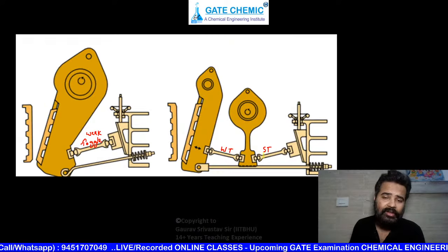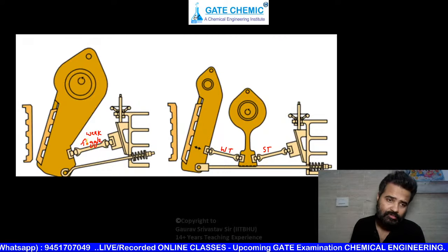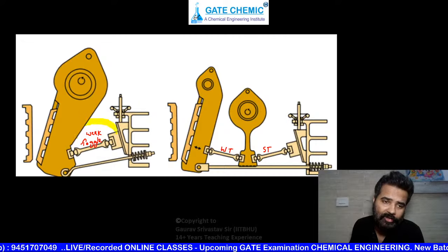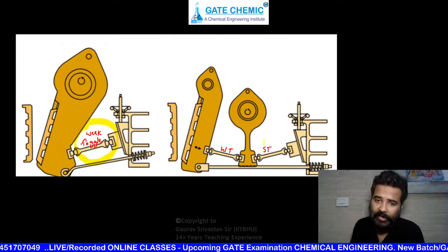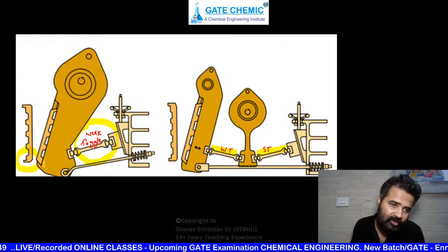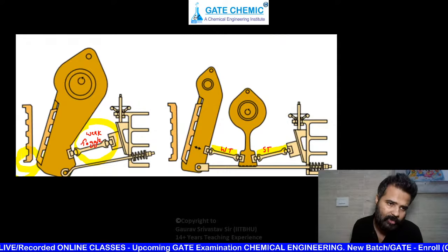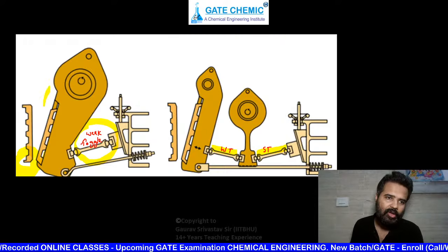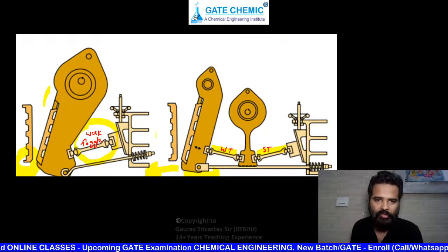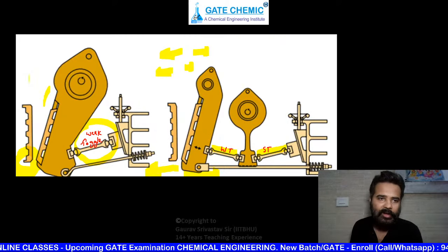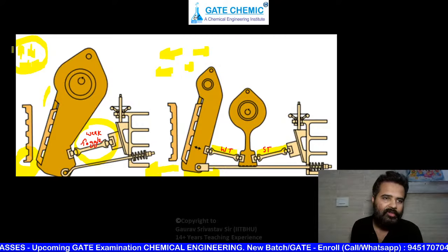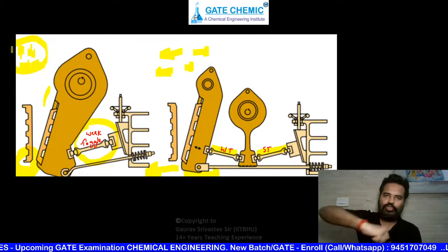And here you can also see that in industries two types of jaw crushers are there based upon toggles. In a few, only one toggle is there. Clearly you can see a one toggle type crusher, and here you can see two toggles. What is the basic difference, beta? Here the movement is like this, going down and up. Here the jaw is moving just forward, backward, forward, backward. But here it is a mixture of these, and you will see that type of motion.